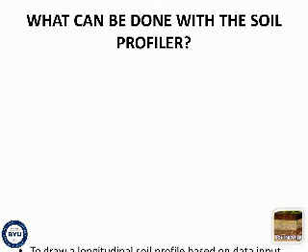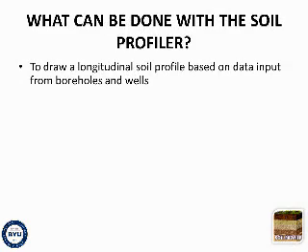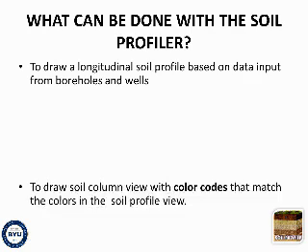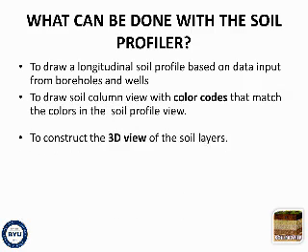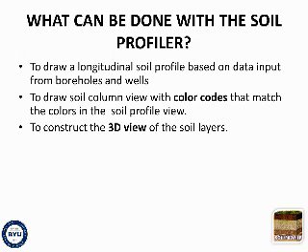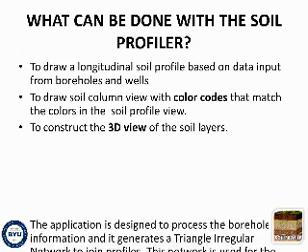What can be done with the Soil Profiler? First, it can draw a longitudinal soil profile based on data input from boreholes and wells. It can draw a soil column view with color codes that match the colors in the soil profile view. And it can construct a 3D view of the soil layers.